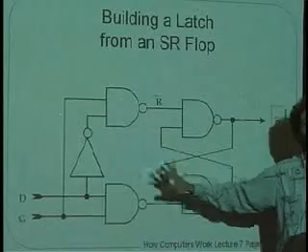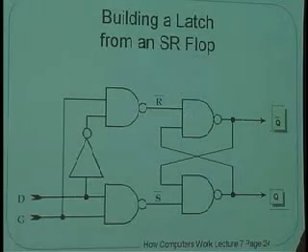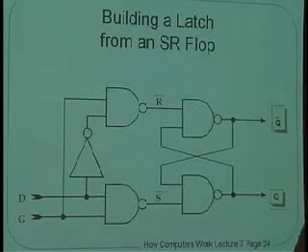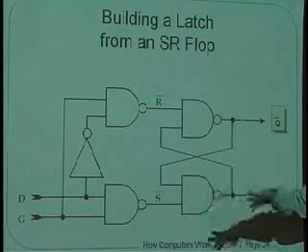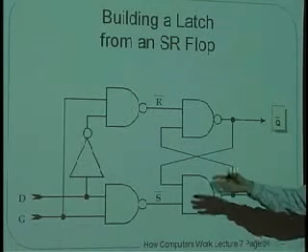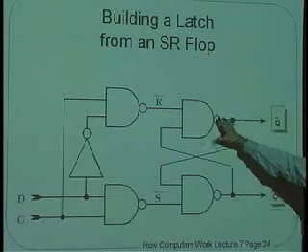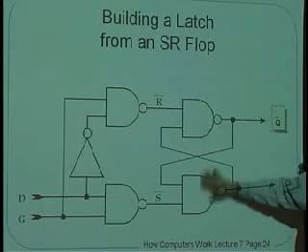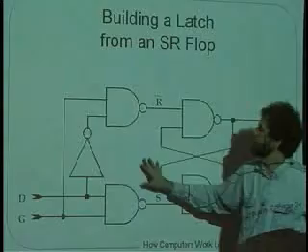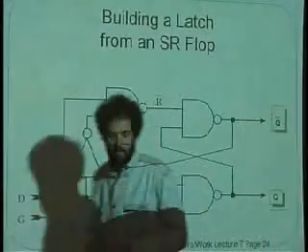This is only done to show you that really there's only one single-bit fundamental mode machine out there, and you can always transform the inputs from one to the other. I can translate a D latch, a transparent latch, into an SR flop and vice versa. This is a way of changing an SR flip-flop, which has a circuit that looks like this, into a D latch by putting some AND gates and an inverter on the input. Nice way to think about this.